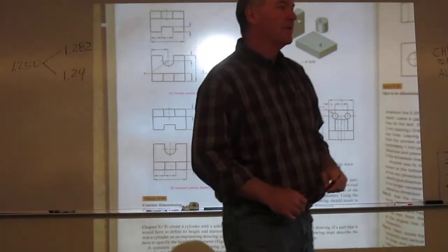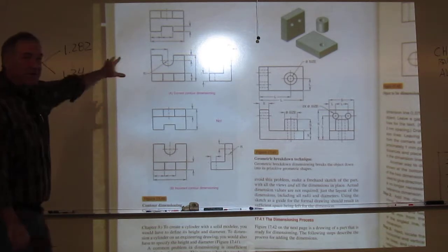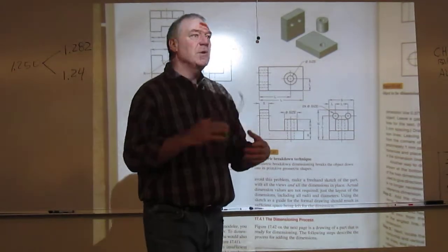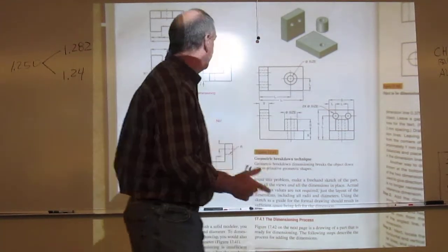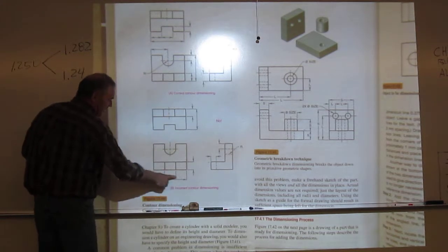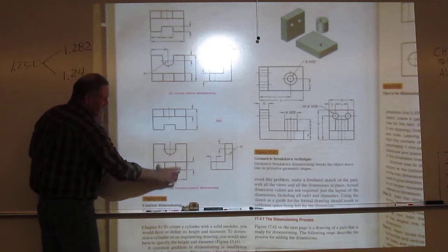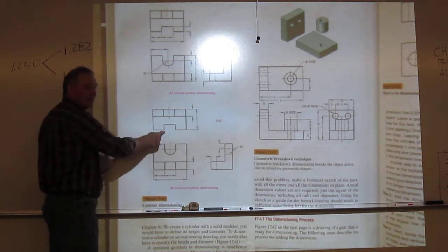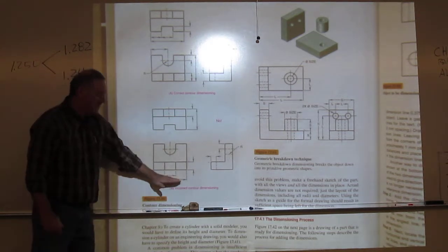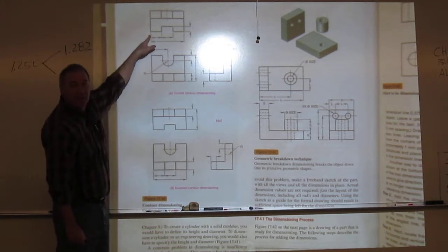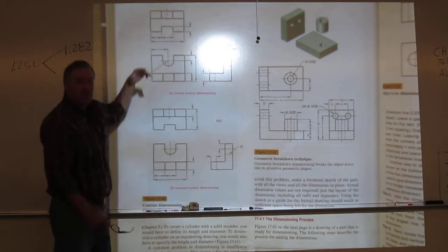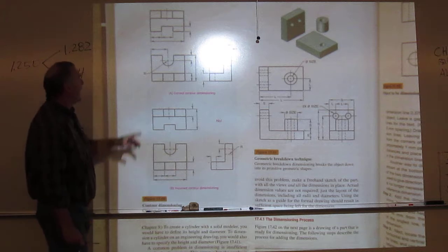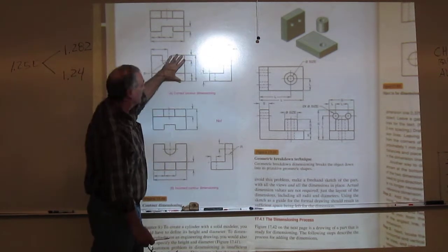That's contour dimensioning. Now, once you go through an object and do your contour dimensioning, then do associative dimensioning with it. Can I move them in between so that I can use them in two different views? Like this one. I've dimensioned down here, but here it's not in between. For me to make the connection from here to here, I have to go through all this geometry to get there. What we're saying is, let's stick those dimensions in between the views like we've done here, and then it makes it very apparent, because we know multi-view, we're just going straight in between all those views. We're projecting straight.